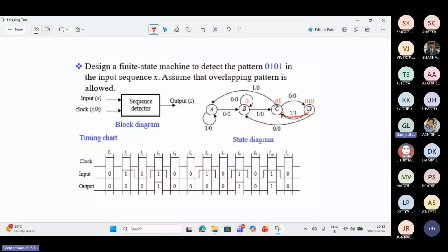So now I go back to the 01 state, and I wait here because 010 is my valid bit sequence, and it becomes optimum if I go back here on 1. If 0 comes, this is not my valid state, so I go back to this state with output 0. Okay, now you check. You start from any bit sequence to any bit sequence.